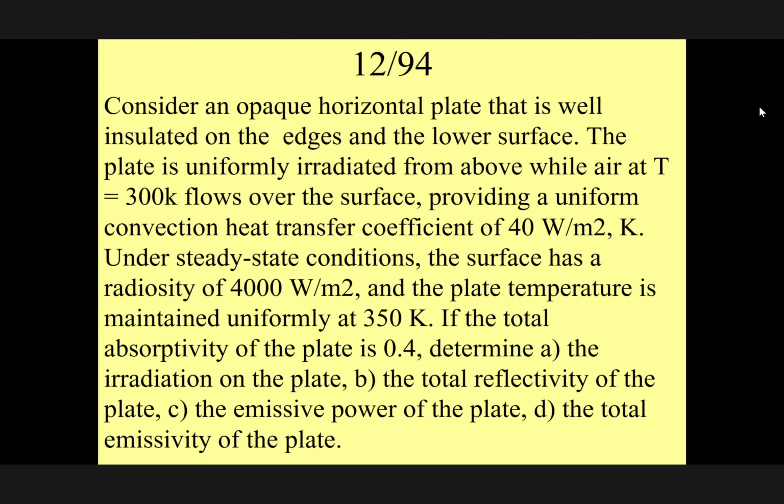The question here is, we have to draw the system to visualize it, and then mention that I'm trying to calculate how much radiation is coming on the plate. How can I do that? Therefore, I believe the first point here is I have to write a simple energy balance for the surface of the plate, trying to consider all the components contributing to that: convection, radiation, and so on. And then if I write the simple energy balance, I can see there has to be some energy coming to the system. Therefore, let's go back again.